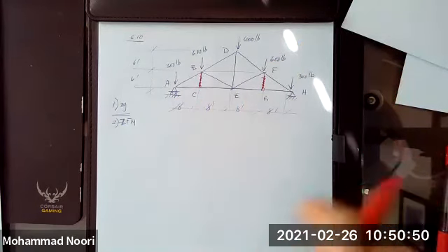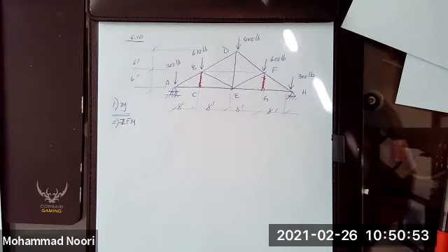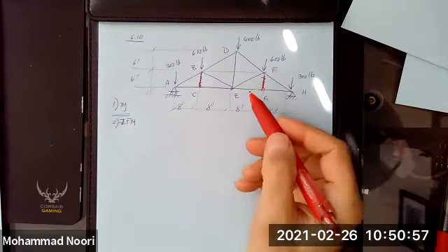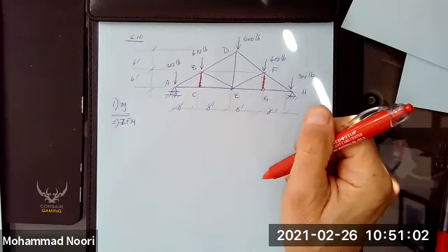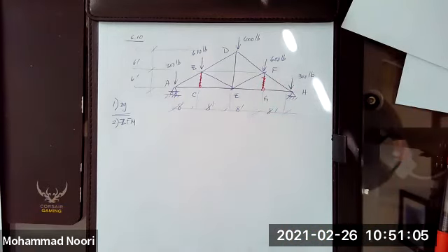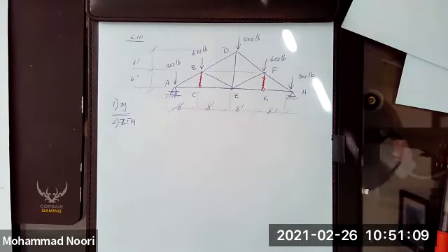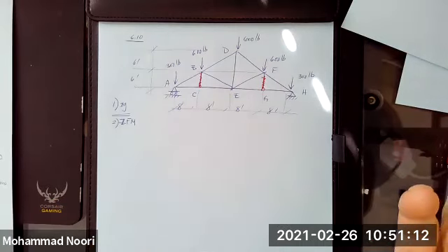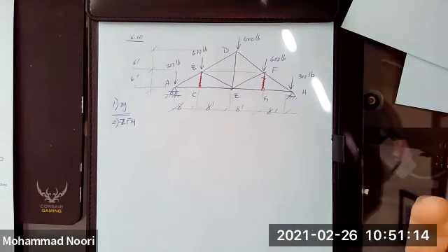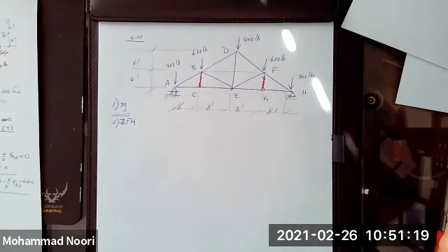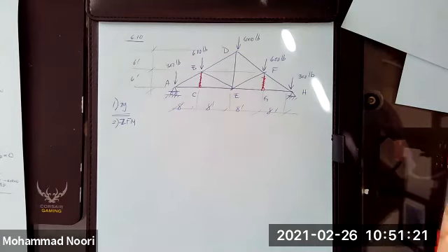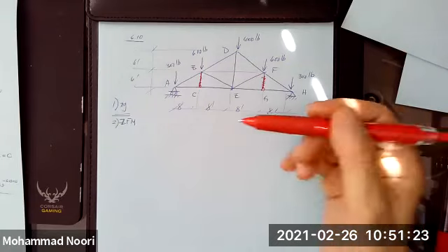And there is no other joint with only 3 forces and 2 collinear. Before you move to the next step, to start with a joint with minimum number of unknowns, let me tell you this. These are, again, important tips that I'm giving you that save you time. Remember, 2 members coming together and no external load, both members are 0. That was the special case of 0 force member. That was the first tip today. The second tip is this.